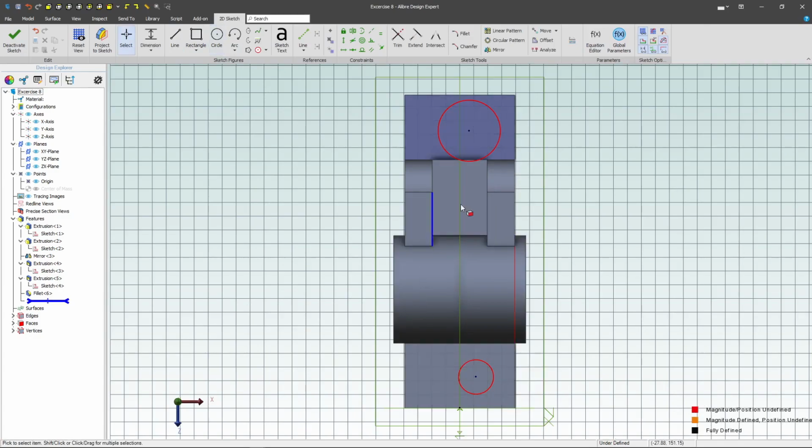And of course, when we talk about doing holes, we'll add an equal constraint. We want to dimension the holes in the ways that they are critical, right? So maybe I have a mating part that's going to utilize these holes, and we want to measure relative to this edge, right? We want to measure where things are important for good quality purposes. Let's give this hole a diameter of 25.